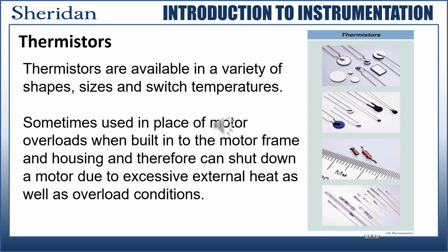Thermistors are available in a variety of shapes, sizes, and switch temperatures. Sometimes they're used in place of motor overloads when built into the motor frame and housing, and therefore can shut down a motor due to excessive external heat as well as overload conditions.